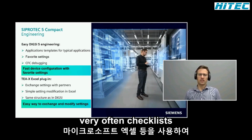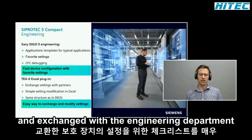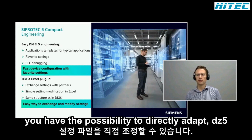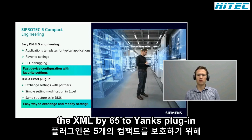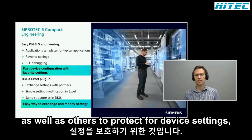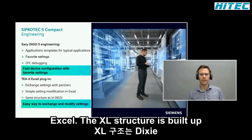Very often, checklists for settings of a protection device are prepared and exchanged with the engineering department using a tool such as Microsoft Excel. And with our TAX plugin, you have the possibility to directly adapt DIGSI5 setting files in Excel. The XML-based DIGSI5 TAX plugin is intended to import, modify, and export SIPROTEC 5 Compact as well as other SIPROTEC 5 device settings using Microsoft Office Excel.